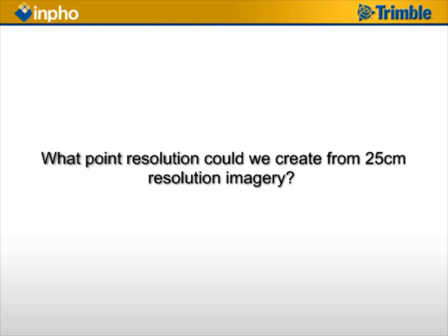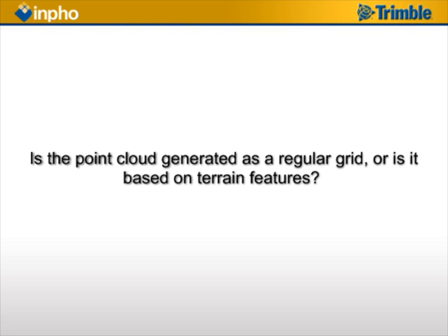Again, the default that we are setting for that would be 3 pixels, just to keep the number of points that we are extracting a little bit lower. But if you don't care about that, so if you're able to handle all the large data sets for your storage or whatever, if you want to have that high density, you can go up to 1 pixel ground sample distance.